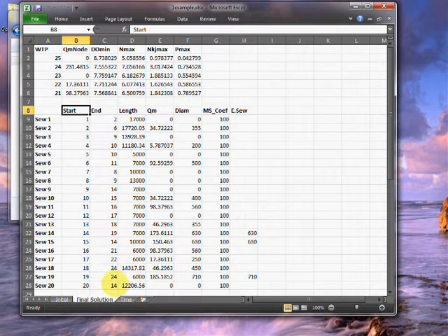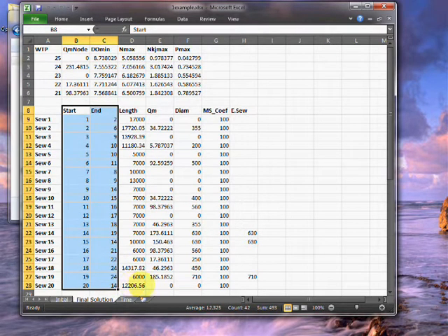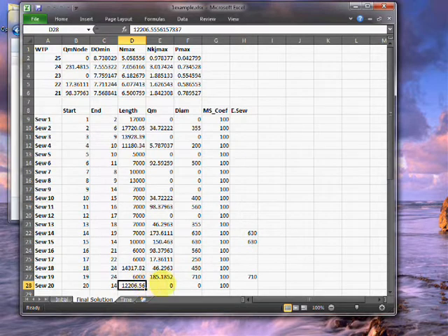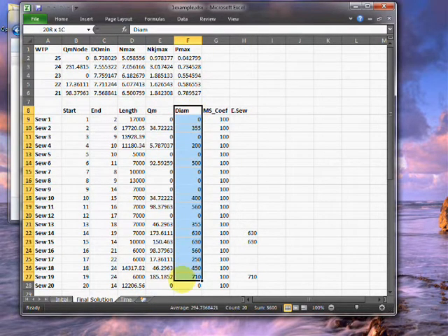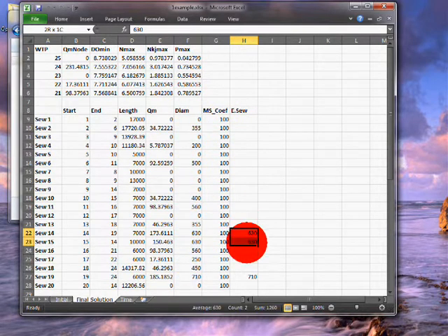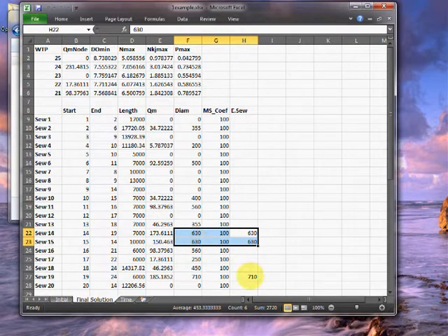In particular, there is information about the minimum concentrations of dissolved oxygen and maximum concentrations of nitrogen and phosphorus. Then, there is information on the sewers, the start node and the end node, the sewer length, the wastewater flow, and the resulting diameter of the sewer, the sewer's Manning-Stickler coefficient, and finally, the diameter of previously existing sewers.